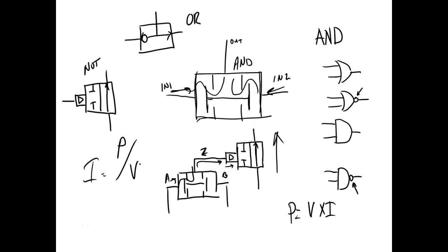But I have to start getting that down close to ground. So what do we start doing? We start stepping the voltage down. Well, if I step the voltage down, the current goes up to provide that power. Y'all understand that? So I have to use larger gauge wires.